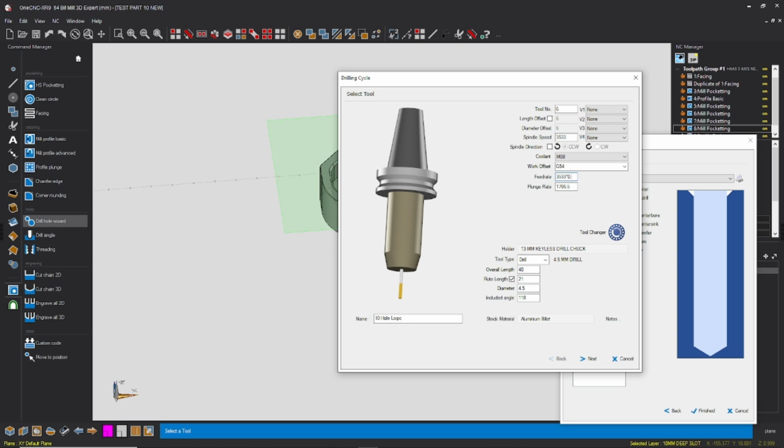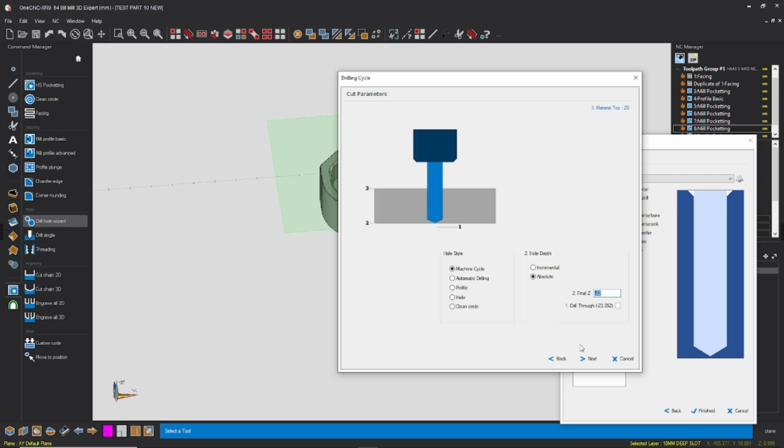353, and I'll times that by 0.08. These are quite bog standard speeds and feeds. Your drill will run harder than this, don't get me wrong, but these are quite safe for various different things you'll be using it for. It's just a good sort of speed, like good generalized speeds and feeds.